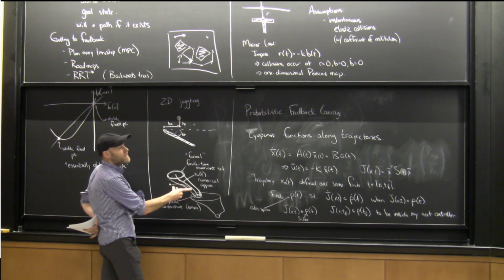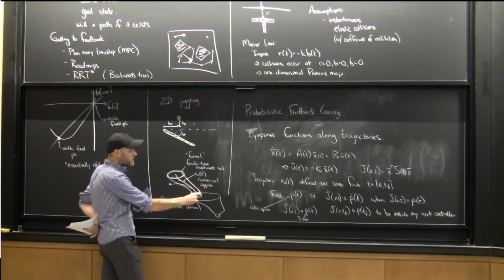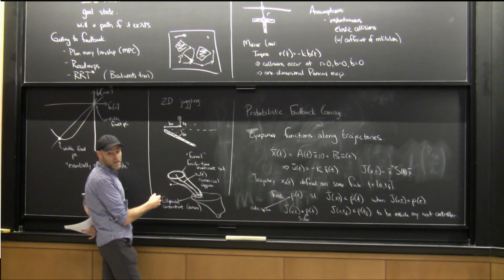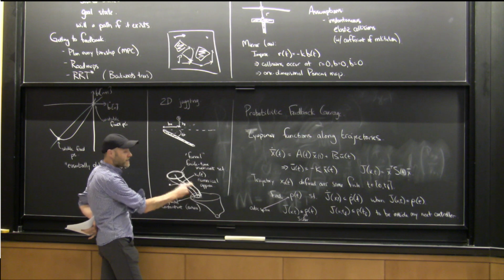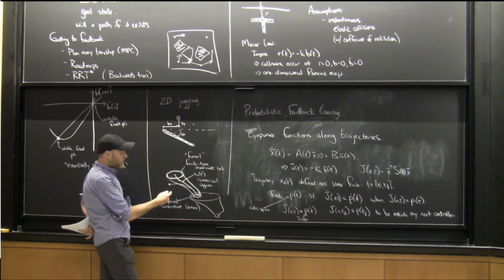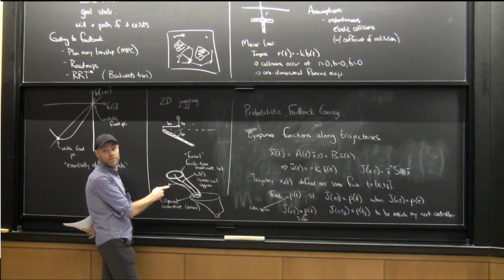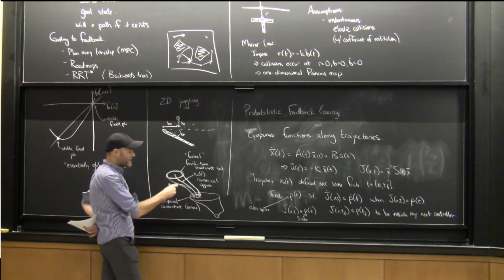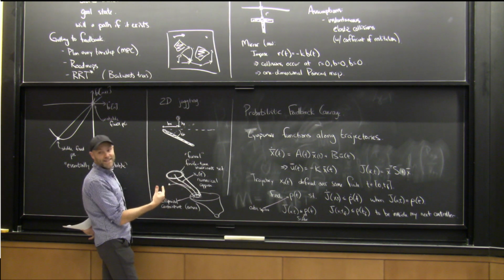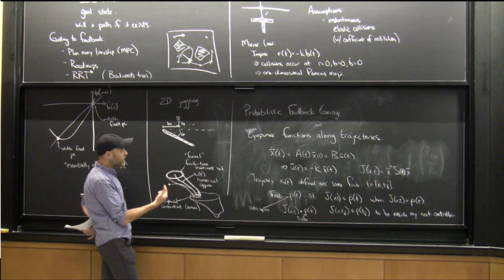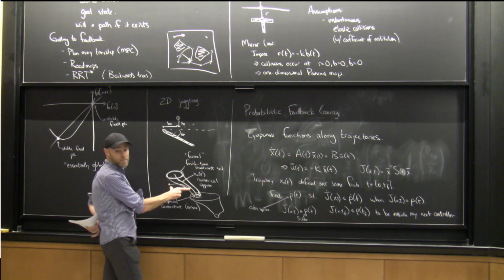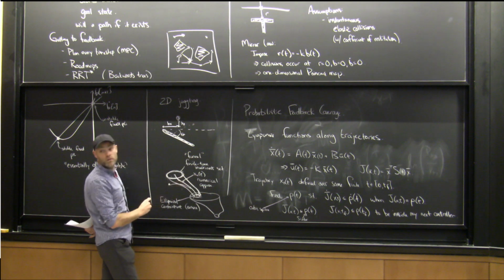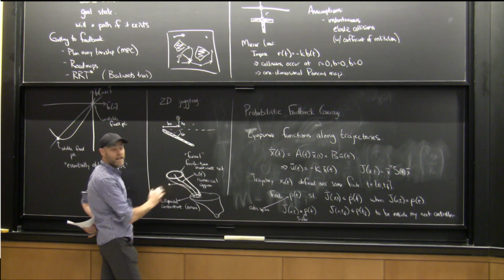The nice thing is that the LQR tree solutions, because they're picking up big volumes of space and you're only adding trajectories outside of those volumes, you end up with a relatively sparse tree. So you only have to do a handful of trajectory optimization problems, and it's therefore somehow it switches the cost, or maybe it's just because the sums of squares cost so much more. I don't know, but somehow the cost is relatively okay to do trajectory optimization instead of some naive forward projection in order to make these edges.